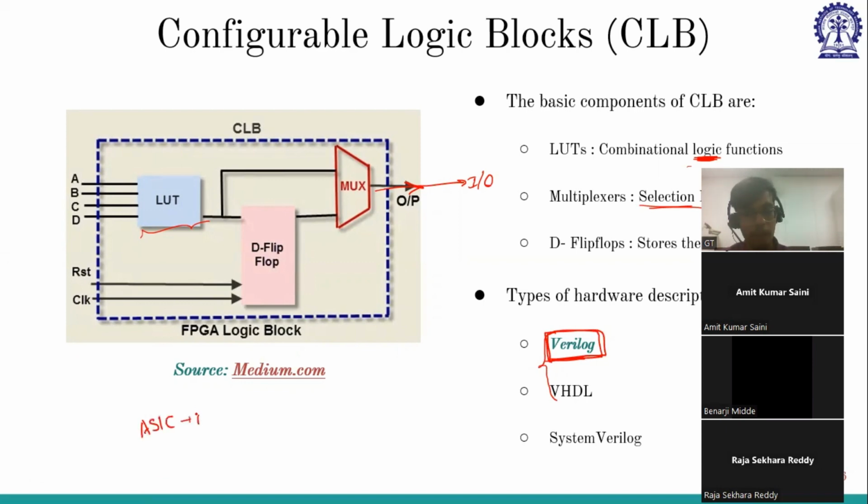So it is very application specific. Application specific IC means integrated circuit, specific to that particular application. You might have seen there are gates, NOT gate, AND gate, NAND gate ICs. They are very specific for that application. In the case of FPGA, you can write code for a NOT gate, then a NOR gate, and dump it again. So you can change it. It is not fixed. You can reconfigure it at any time. Depending upon the code that you are dumping, it will change accordingly.